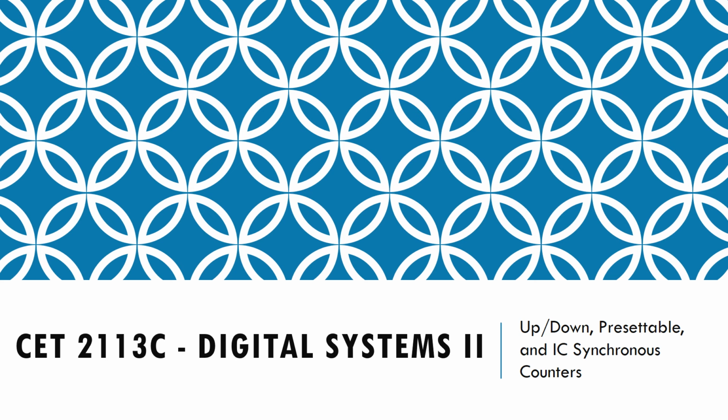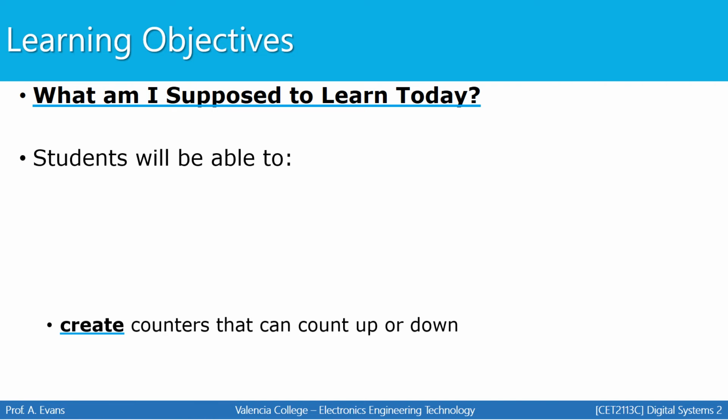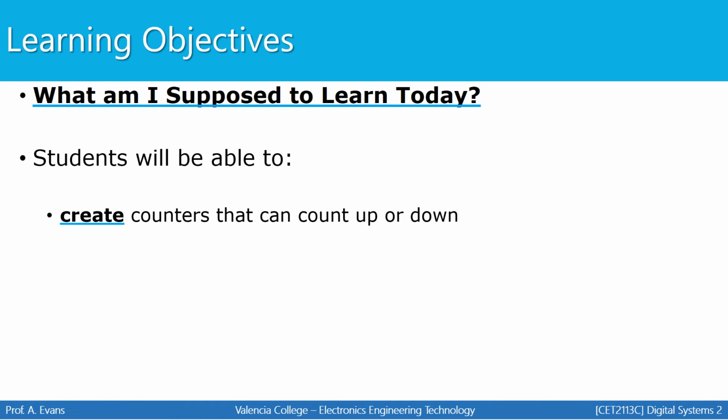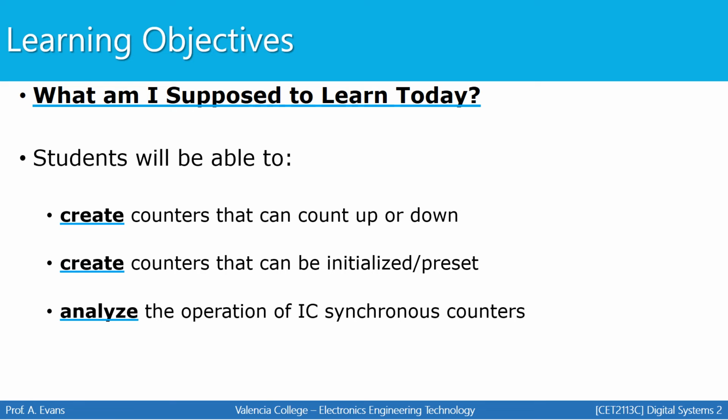Welcome to Digital Systems 2, and in this first video lecture we are going to discuss up-down, presettable, and IC synchronous counters. By the end of the video, you should be able to create a counter that can count up or down, create a counter that can be initialized or preset, analyze the operation of an IC synchronous counter, and decode any state of a counter. Those are our learning objectives in this video.